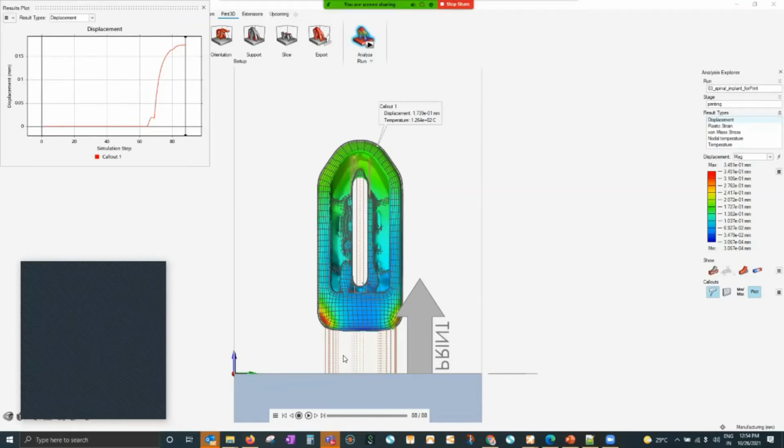The reason industry doesn't do that normally is that you have to remove this support, and removing the support will require a machining operation, right? If you put this part directly on the base plate, it will be firmly attached to that base plate, and while removing it will be difficult.